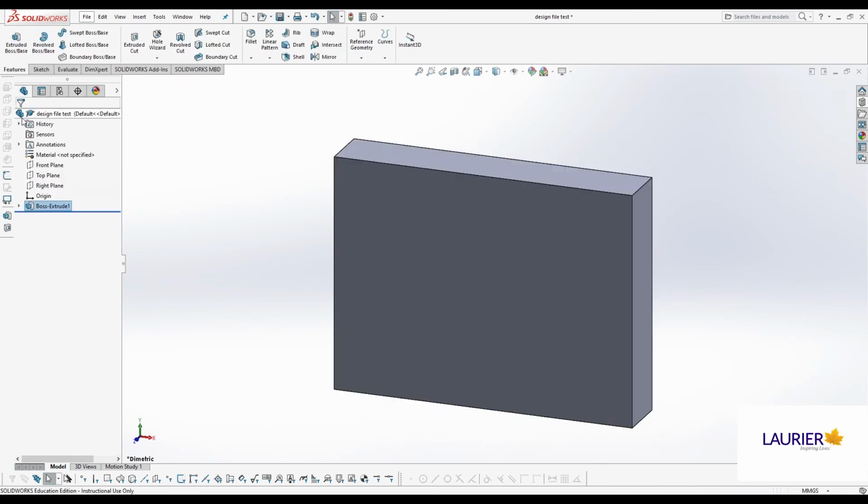And I've got my 3D part called Boss Extrude 1. I don't know about you, but when I have a newborn baby, the first thing I want to do is name it. We're making a pretty simple object, but if we're making a more complex object, we don't really want to leave it with these default names. Because if we've got, say, 30, 40, 50 different features in an item, and then we come back to it, say, 3 months down the road, we haven't looked at it, we got busy with something else, we came back to it, and we've got these default names, we're not going to know which is which.